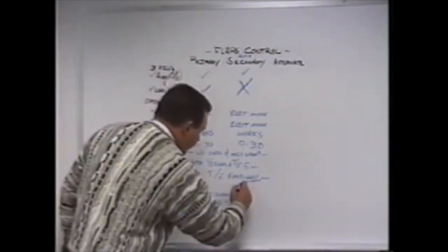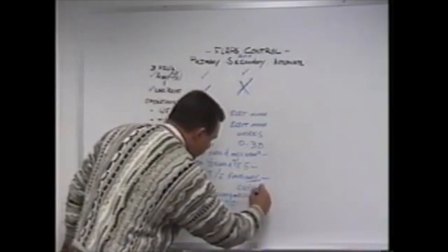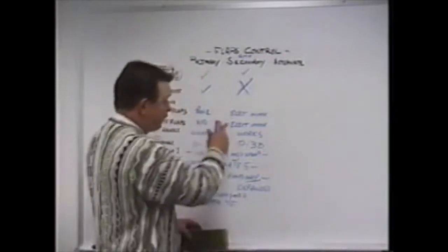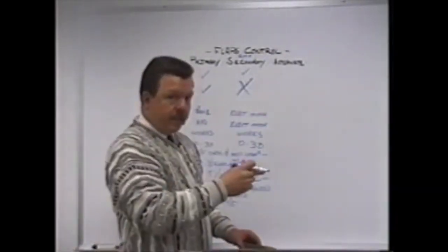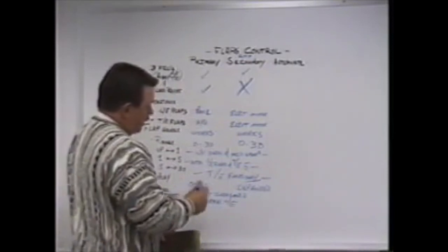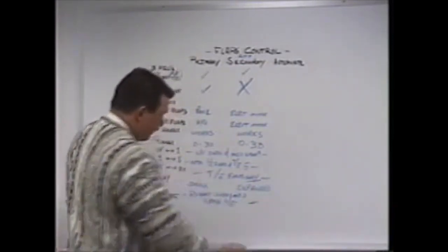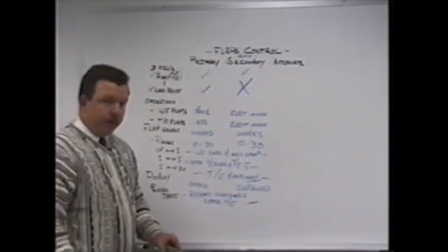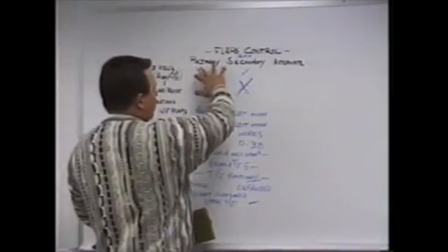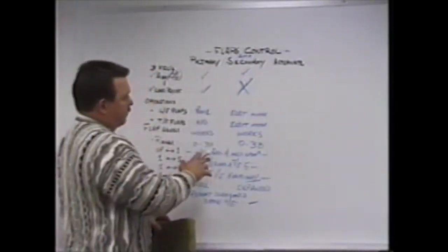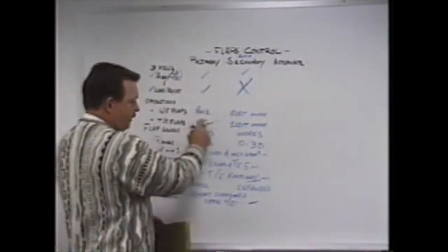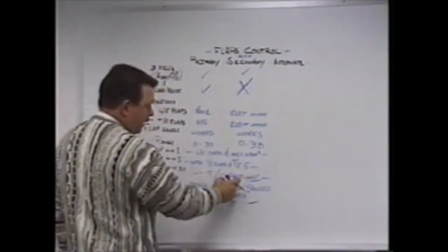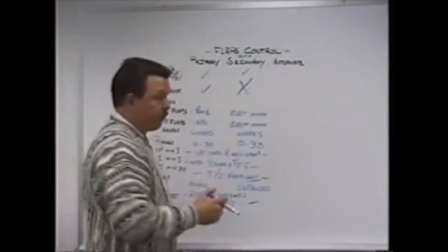Your display in the secondary mode is expanded. You have 4 vertical tapes for your trailing edge flap segments and 6 leading edge boxes for your leading edge segments. Again, going into reverse thrust will retract the inboard and midspan leading edge flaps in the secondary mode. Basically, the only difference between primary and secondary is the amount of time to operate the affected set of flaps, because electric motors are a lot slower, the display, and no load relief.